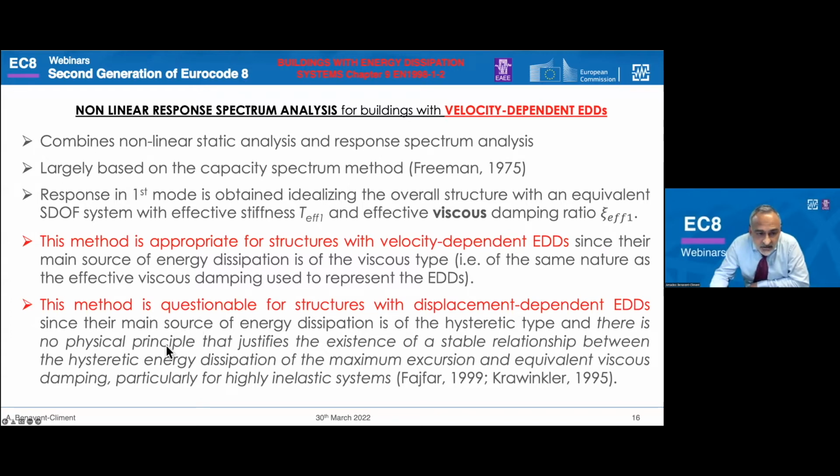And there is no physical principle that justifies the existence of a stable relationship between the hysteretic energy dissipation at the maximum excursion and an equivalent linear viscous damping, particularly for highly inelastic systems. And we have to keep in mind that these types of structures are highly inelastic, since the energy is dissipated mainly through large plastic deformations on the displacement-dependent dampers.